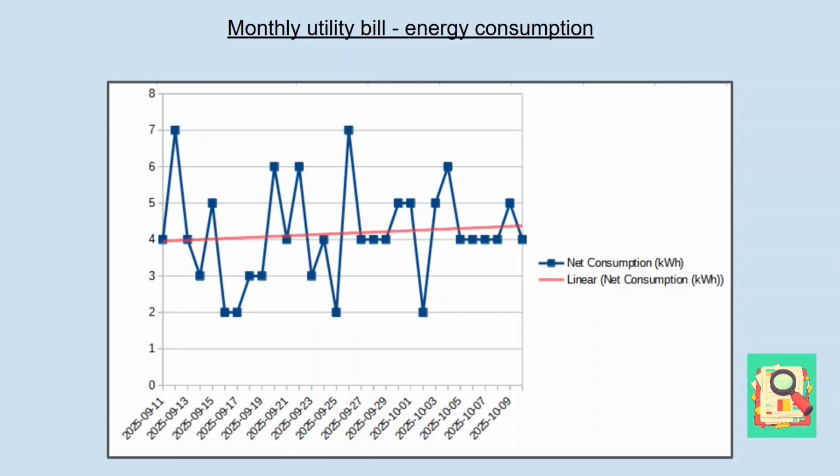Now, to size the batteries, we can use the energy consumption graph, but we need it to have a higher resolution. A resolution on a 24-hour basis. When we have the energy consumption on a 24-hour basis, we simply find the area underneath the energy consumption graph. That would give us the rating of the battery in terms of kilowatt hours. Lastly, to size the solar panels, we can use the methods shown in the previous slides.